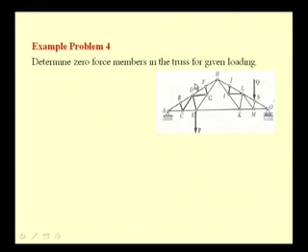So, now we can see other joints if the special condition exists in the constituent members. Let us move to this joint at C. We have already seen that this member BC has to be a zero force member and AC and CE are collinear. So, if a force exists in this member CD, then its vertical component cannot be balanced, and this renders this member CD to be also a zero force member.